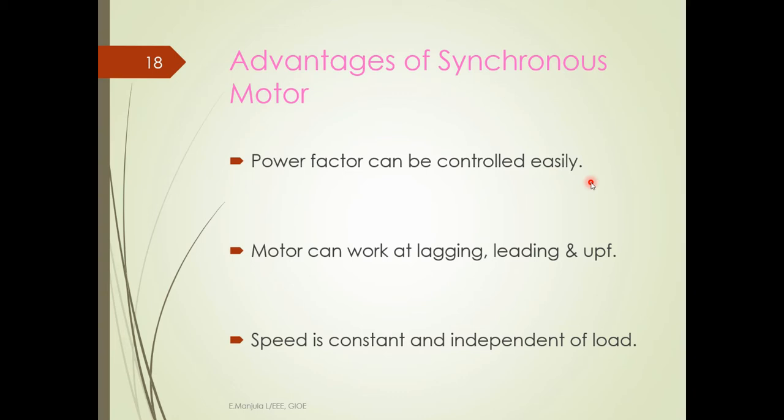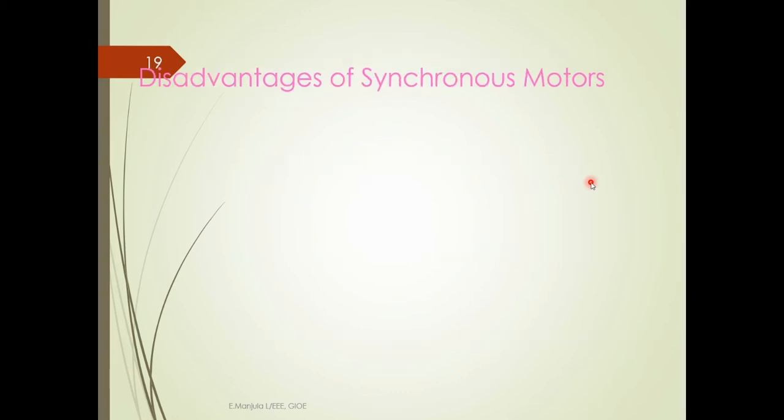But yes, it has two states. Either it will rotate at synchronous speed or else it won't rotate. So, for example, if the load on the motor increases, if it has been overloaded, then what happens? It directly loses synchronism, hence the motor won't rotate, it will stop.